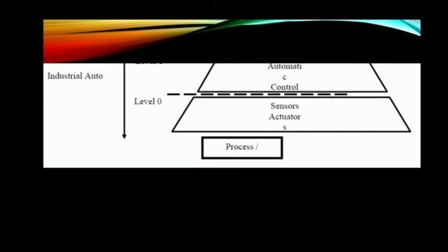These computed control inputs, which again are in convenient electrical or pneumatic forms of information, need to be converted to physical process inputs such as heat, force or flow rate, before they can be applied to effect the desired changes in the process outputs. Such physical control inputs are